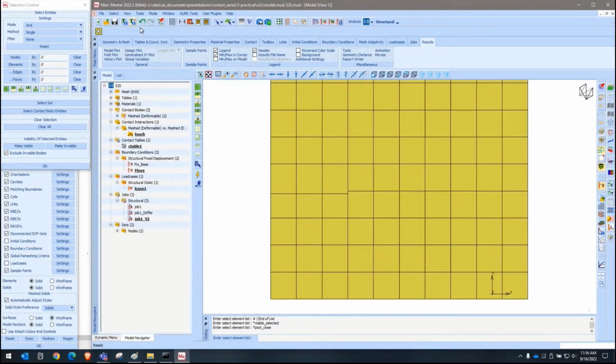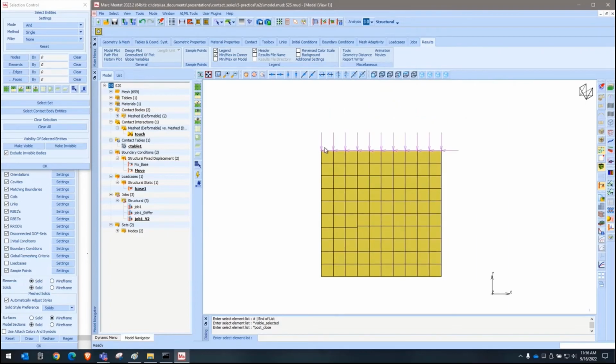So just getting back to my original model, if instead I applied a load instead of enforced motion, all that'll happen is this thing will move more and will penetrate more, but the same load should be applied to that tip, so you should get closer to the answer. But the moment you have enforced motion, your stiffness is critically important. So in that case, you have to use higher stiffness for that jointed connection.